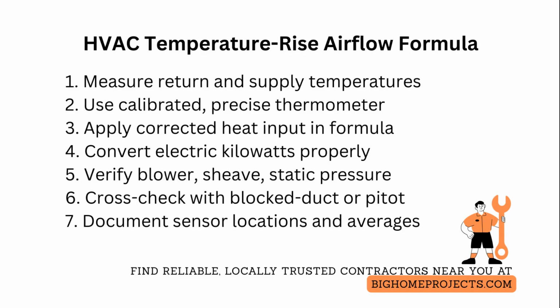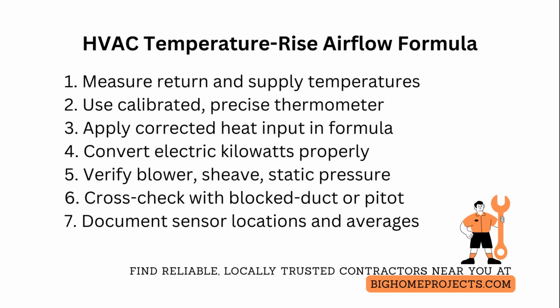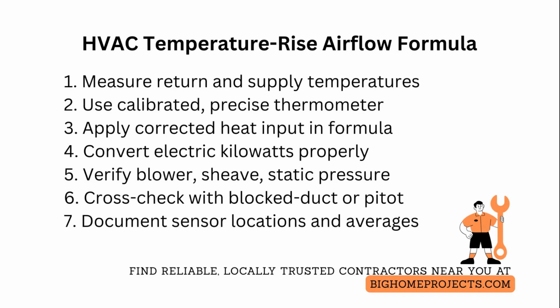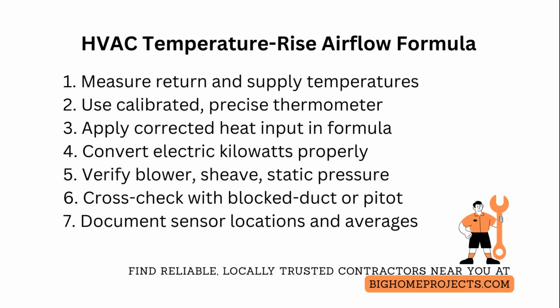If using electric heating, use measured kilowatts converted to British thermal units per hour by multiplying by 3,401, then divide by 1,200 times the rise. Always verify blower wheel diameter, motor sheave settings, and static pressure before concluding the CFM. One misaligned sheave or plugged filter can make the calculated CFM meaningless.